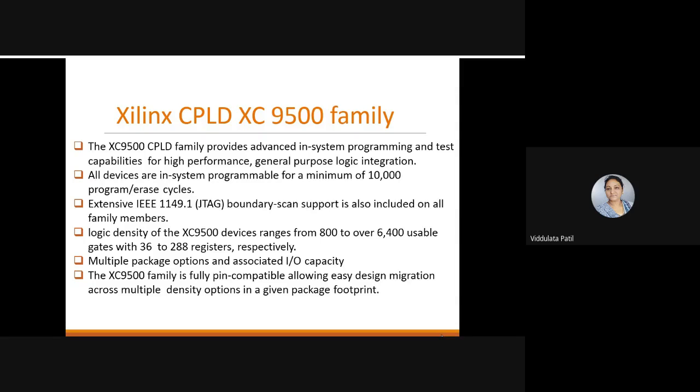But if we have a facility such that we can program that chip while it is on its board itself, that is advantageous because it makes the system easier to program. Then we call that in-system programming, where the chip is on its board and we are programming it there.